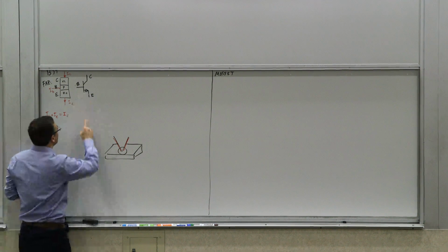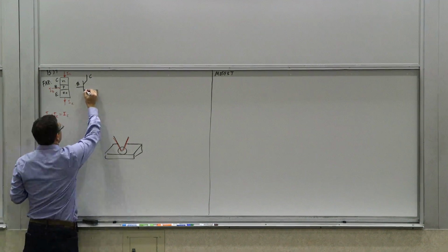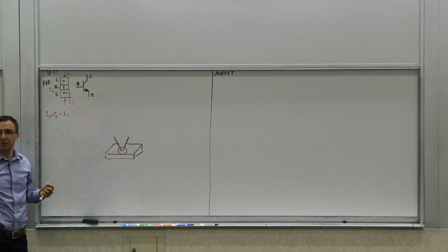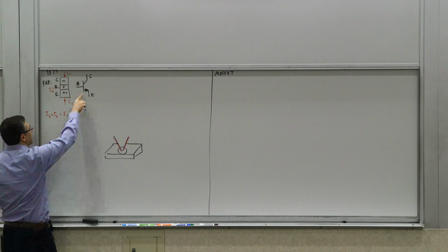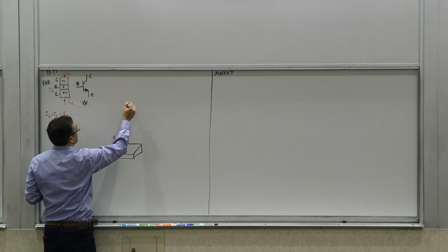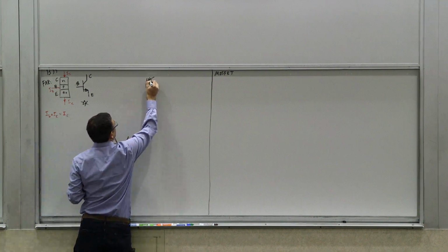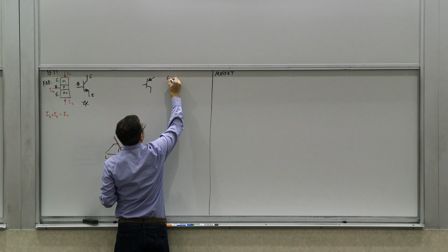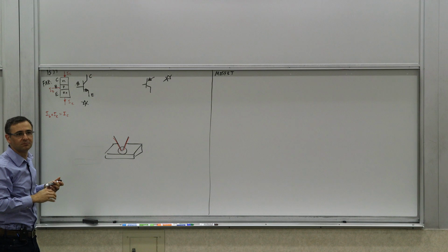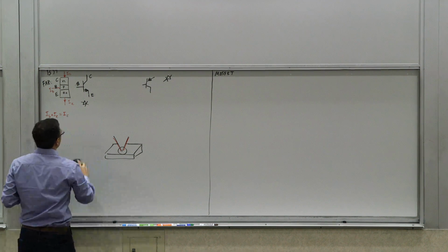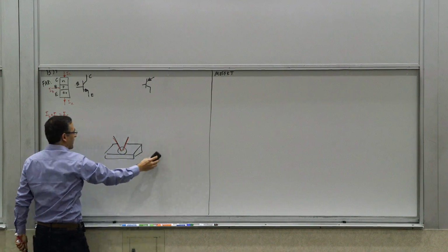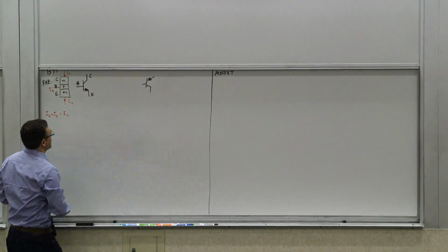The other thing about the symbol is that you differentiate the NPN and PNP by the direction of the arrow. The arrow is always on the emitter. The arrow coming out implies that this diode is pointing this way. And the arrow going in, which is the case of the PNP, means that this diode is pointing this way. So those are the mnemonic devices, quote-unquote, to help you understand what that is. But that's the big picture. Anyway, that's a historical aspect of it.